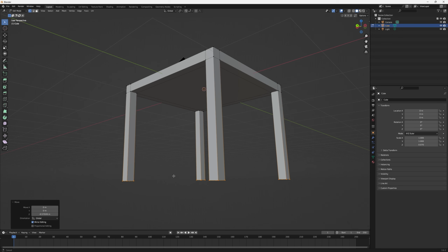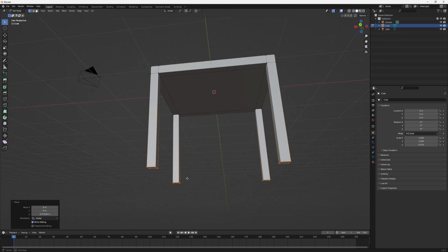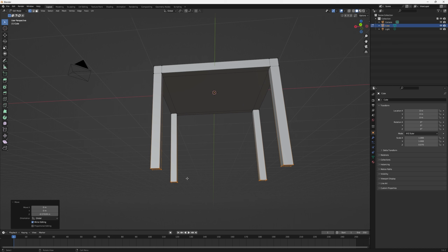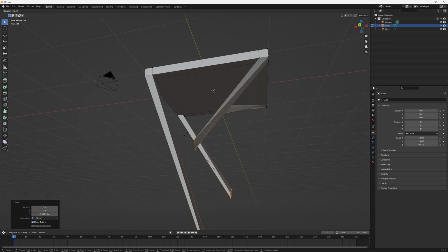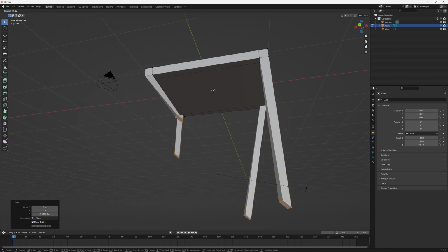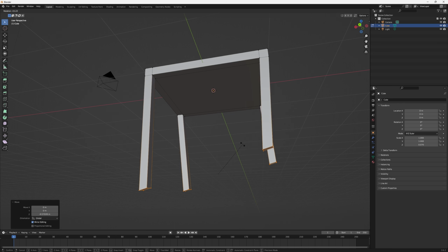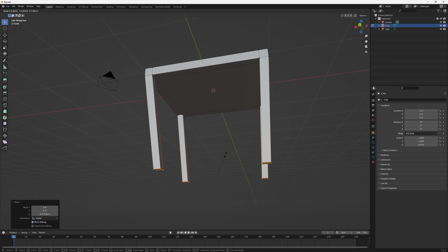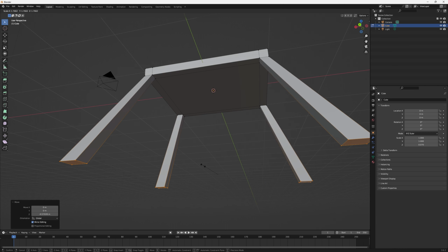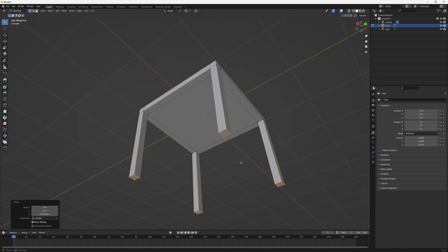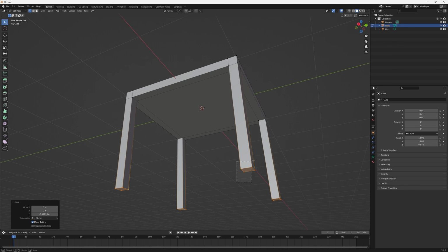And remember, most of our previously mentioned operations like rotation, movement, and scale, they all work for these individual components like vertices and edges and faces. So for example, I can, of course, rotate these vertices if I want to, or I can scale them like that, right? And if you don't want to do that, you just press the right mouse button to cancel the operation, right? Of course, I can also just select these four.